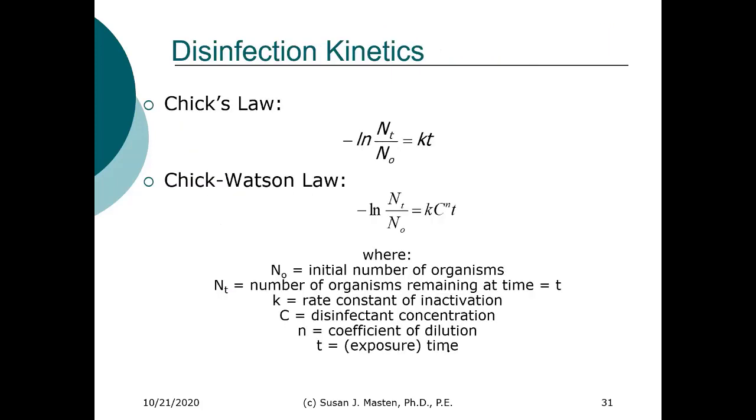Now, we can model disinfection kinetics with a first order reaction. So this is a simple first order reaction where we're modeling the concentration or the number of organisms at any time as a function of a constant and time. That's Chick's law, developed in the 1920s.